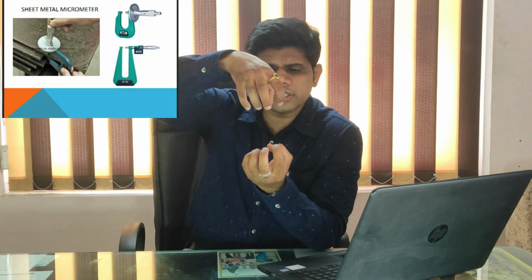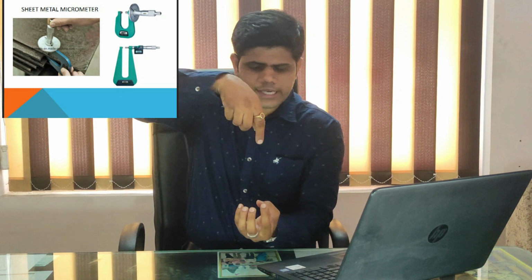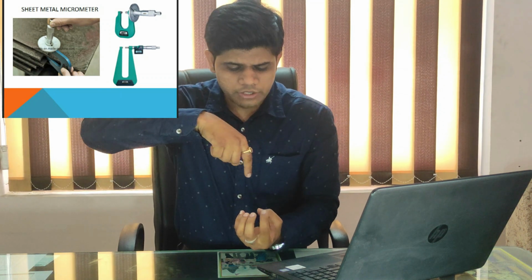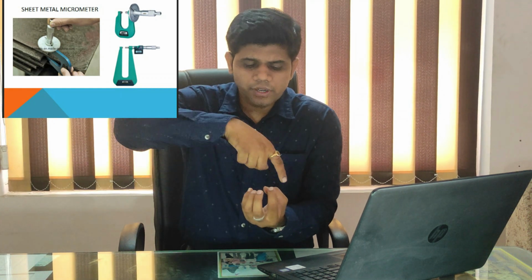The first one has a vernier, where the thimble is on the top. If you are measuring like this, you have to see the micrometer's scale from the top, where the thimble is on the vertical portion and not the horizontal portion. In the vertical portion you can see exactly what the diameter is, and you don't have to move your face.